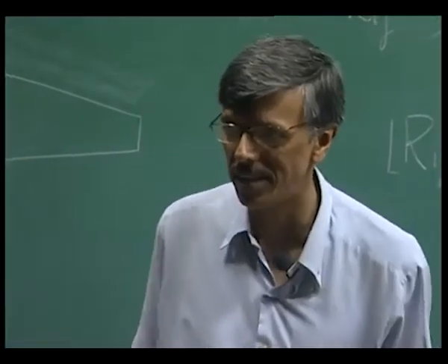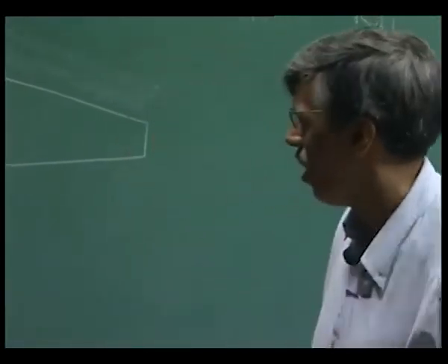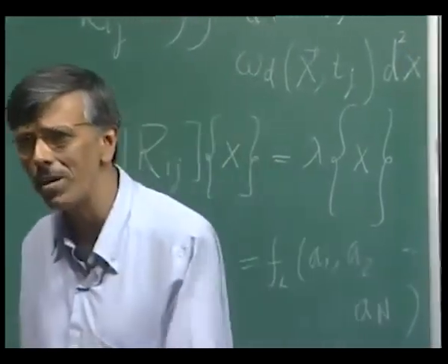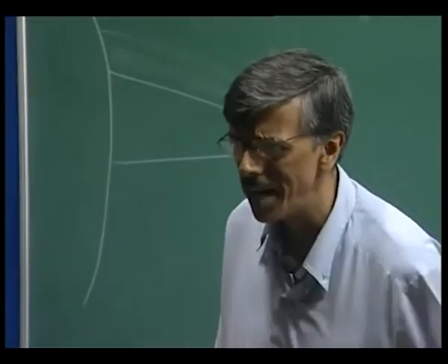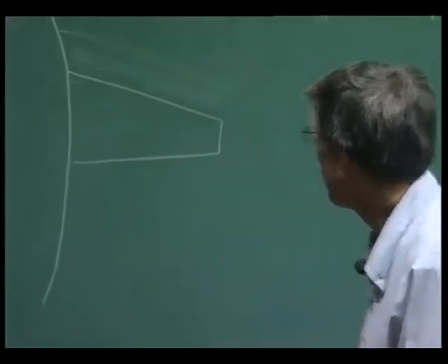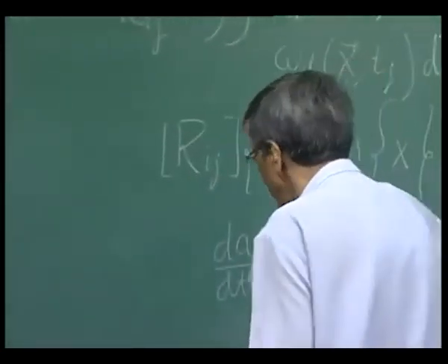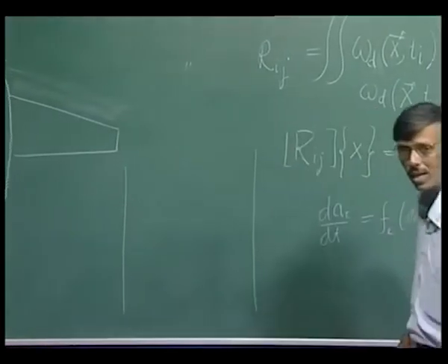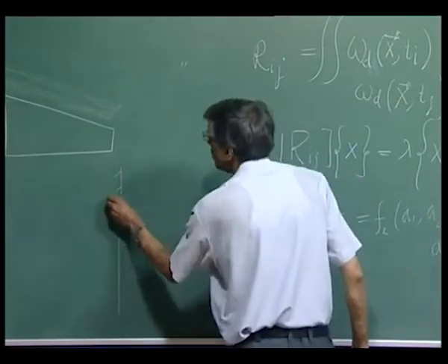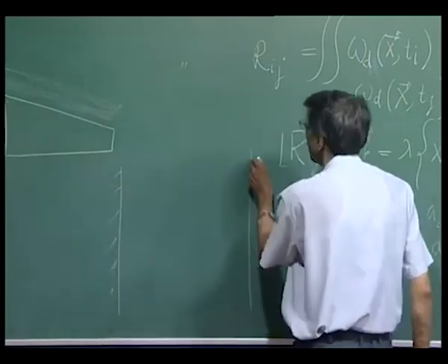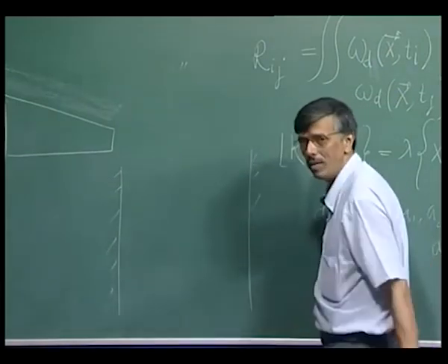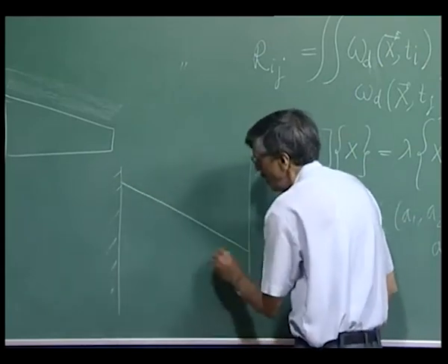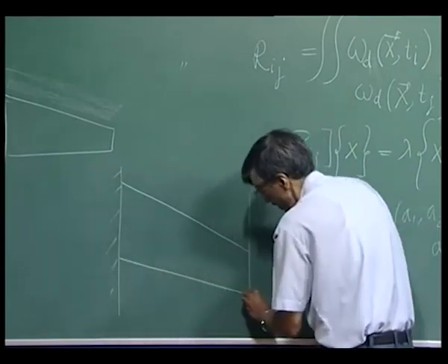So, whenever Re theta is greater than 100 or Re delta star is greater than 245, you see the flow becoming contaminated right there. So, how do they do this experiment in the tunnel? It is fairly simple. If you have a tunnel like this, so these are your tunnel walls, then you fix a wing from tunnel wall to tunnel wall.